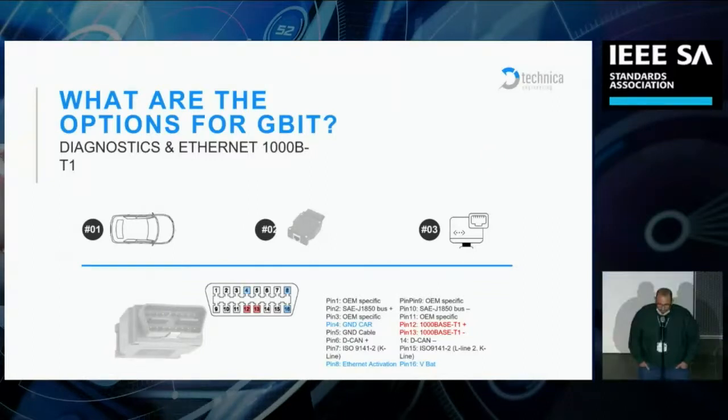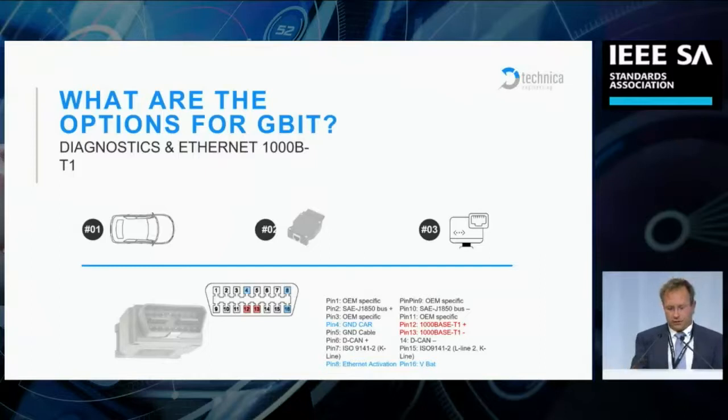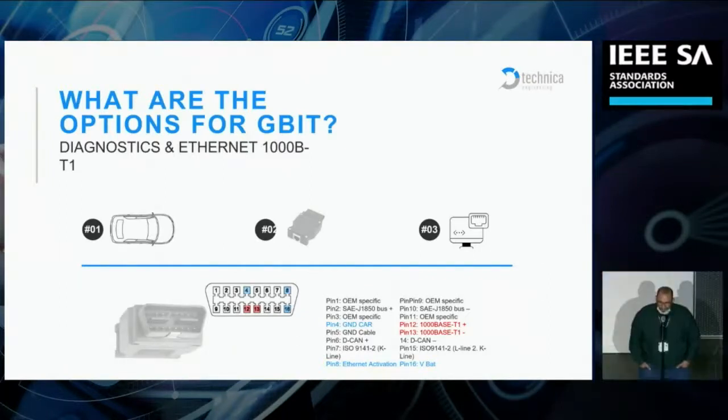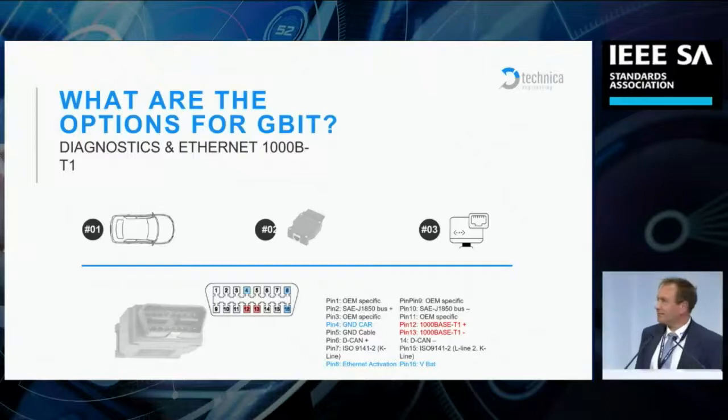Yeah, so the idea was I suggested why not investigate 100BASE-TX, because you can use the 4 pins as 100, but that's not common in laptops. So the question for them is, how can they just use a laptop to connect to the vehicle? Yeah, so the message is use a media converter outside of the car. It's supplied by the power supply of the OBD connection, so there is no impact. So you connect the connector. In the connector, the media converter is directly placed outside the car, part of the diagnostic system, and the job is done. So I think what we need to do is get offline, me and you, and we should take this as a proposal because we're working on this now. So if you have something, then we should work on it. You're welcome. Okay.